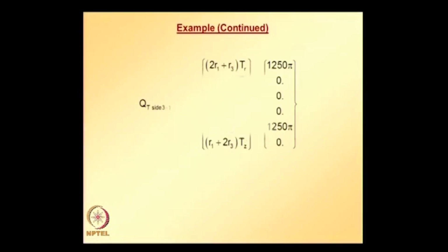Once we have this information we can plug it into the formula that we already derived for uniform traction components, the equivalent nodal load vector for a 3 node axisymmetric linear triangular element. Please note that we do not need to assemble this equivalent nodal load vector for the other edges or sides, because no traction is specified over the rest of the model.